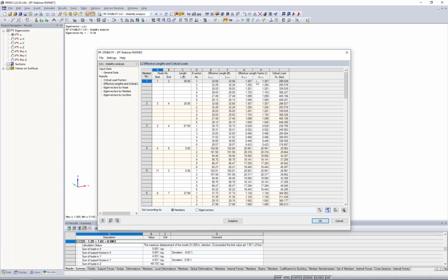We want to input a correct effective length factor for the AISC design, and generally these are given to us from the general tables for pin-fix conditions, but the program here is giving you the true effective length factor for the strong and weak axis based on this buckling mode. So it can be pretty powerful, and I'll show you in just a minute how we can incorporate this with our